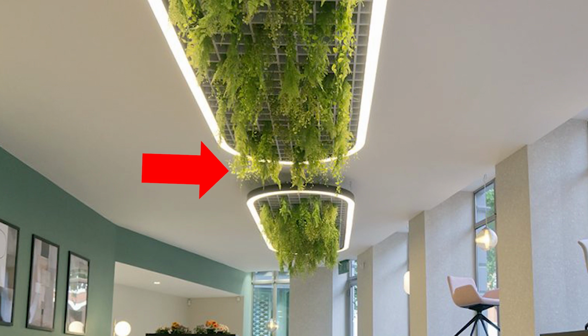These grass elements that we see here, I would make as a separate family, then I would insert them randomly within this grid. And then finally, the only part that is lighting fixture within this geometry would actually be this border here, which looks just like an integrated LED element. So let's do it this way. Let's break it down into a horizontal curtain wall system, which we're going to build directly into the project, mixed with these individual vegetation families that get inserted randomly within this grid, and then finally a LED strip lighting fixture family that will be inserted along the edges. You can also do it along the curvature, but it's a little bit more difficult.